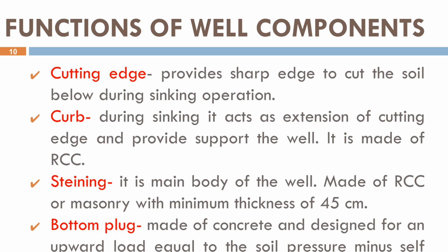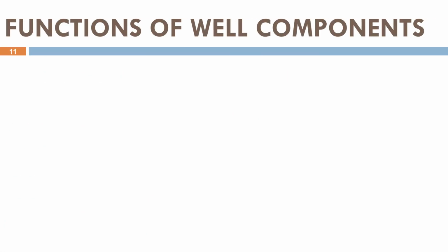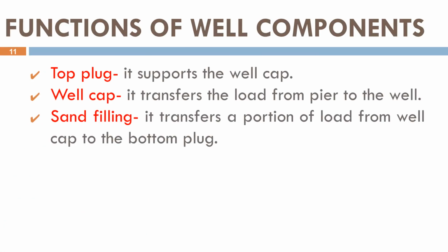After reaching the desired depth, a bottom plug made of concrete is placed to seal the base. The hollow portion is then filled with sand, which helps distribute the load. Finally, the top plug and well cap are constructed to transfer loads from the bridge pier to the foundation.